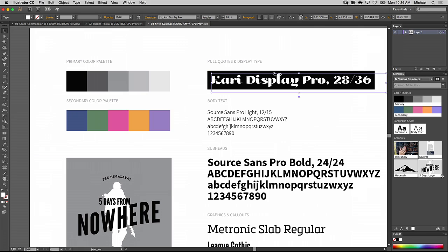added to this library as well, because I'm going to be working on a document in InDesign, and I want to share the paragraph styles that I've defined in Illustrator and use them over in InDesign. Who's wanted that for a really long time? Go ahead and click the Add Paragraph Style button. We'll go ahead and give that a name, call it Pull Quote.